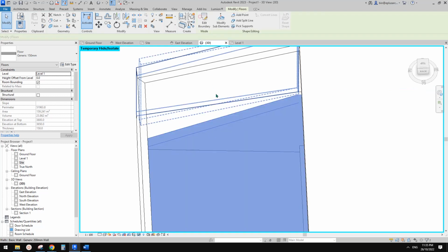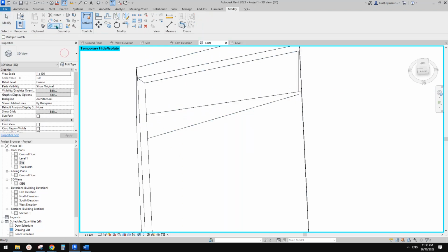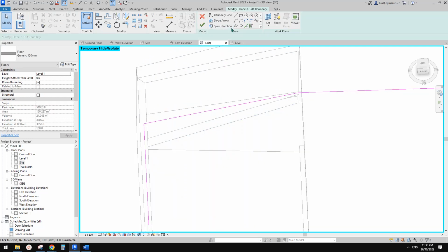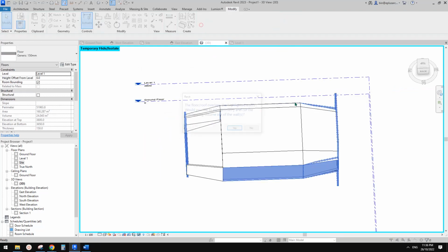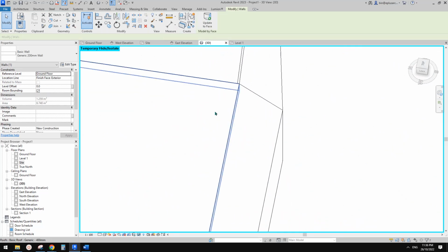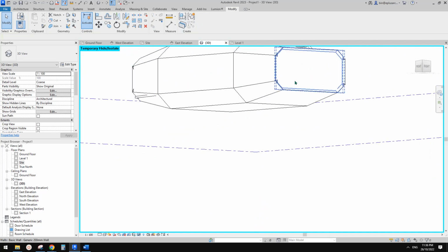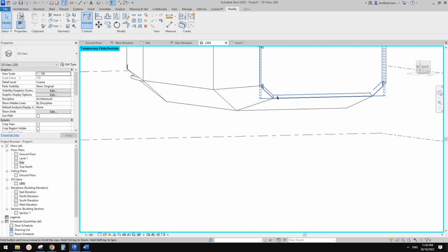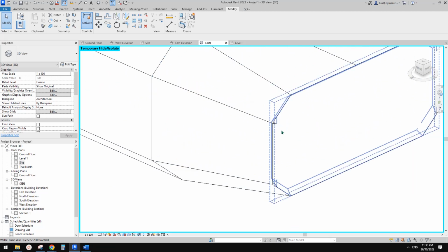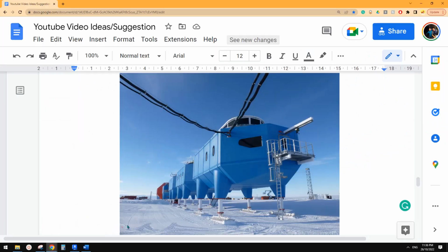Okay, so what we need to do is switch join order, and now we can select the floor, edit boundary. So we have an edge we can pick, and we can trim. Oops, Control Z, TR, trim, and finish. So now that's it. Okay, so this floor is matching the wall. It looks like it's still not 100% perfect, but maybe just model something to fix that. And other than that, I think it's all good.